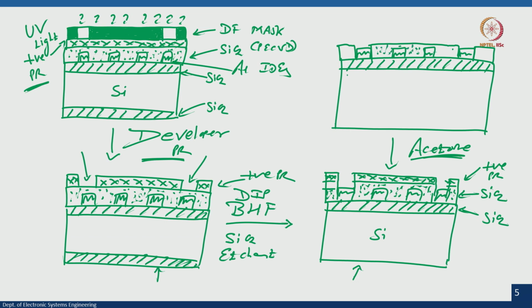I just wanted to show you the example of how to use the dark field mask and how to take the contact pads out, right. These are contact pad 1 and contact pad 2, correct, from the interdigital electrodes. But how to use the bright field mask and how to use the dark field mask, that was the whole purpose of showing you this particular pattern.